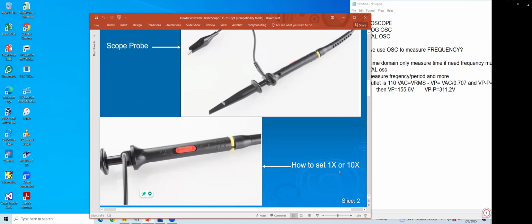So if you are using this adapter shown here and you use 10x, you turn to the right. That means if the signal is too big and the scope cannot display it, then you have to set it to 10x. Normally 1x, which means exactly whatever you see. If you get a question, anything, you have to stop me.